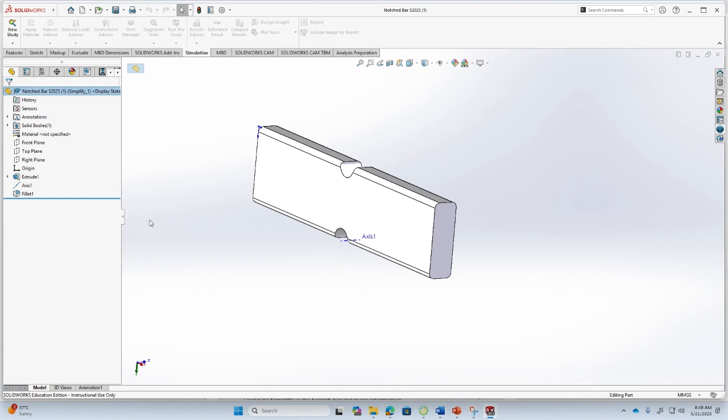Like I told you, you are going to divide it into elements. So for this narrow region, you'll need much smaller elements as compared to the rest of the part, right? So firstly, meshing this region will be difficult. But secondly, let's say if in the original model there were 1000 elements, now because of this region you may unnecessarily need 2000 elements, with many smaller elements to capture the stresses correctly here, okay.